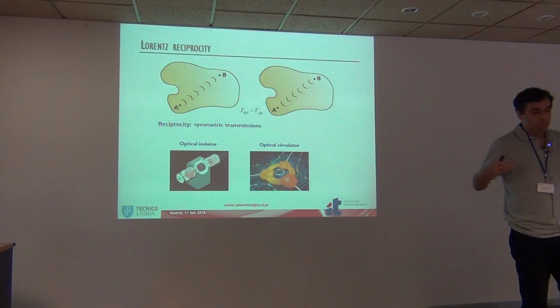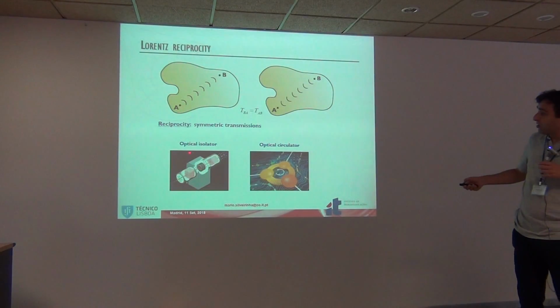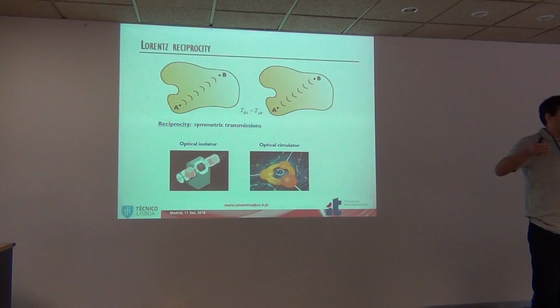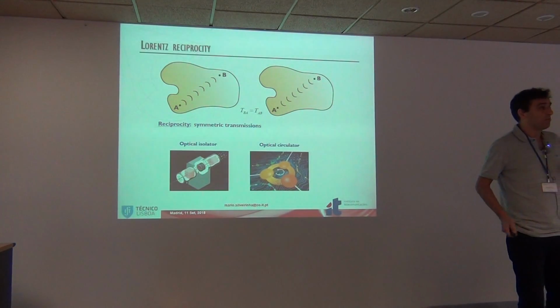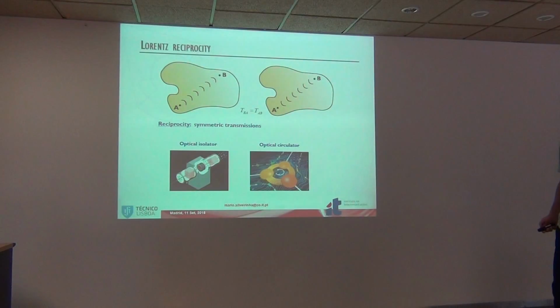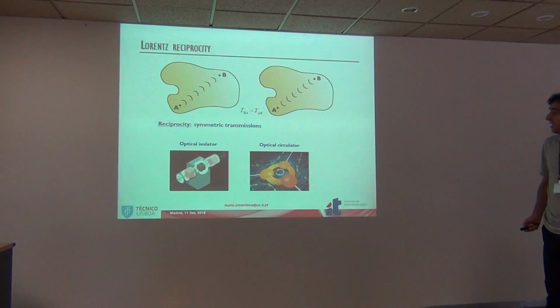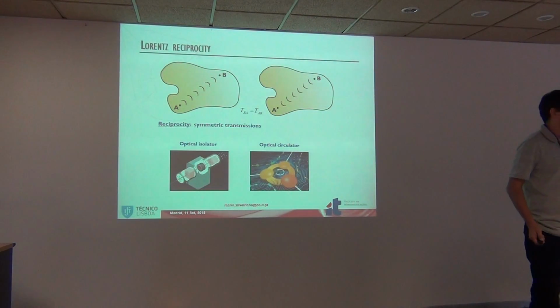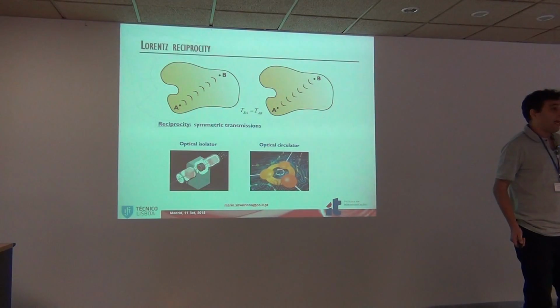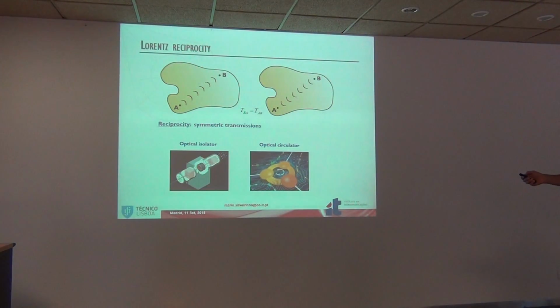Sometimes people say that an optical isolator at optics has the same physical length as an optical isolator at microwaves, because the effect of the non-reciprocity is quite weak. So people in recent years have explored different solutions to have strong non-reciprocal effects at optics. And I'm going to tell you about a particular solution that we developed recently, that allows you to have this without magnetic fields.